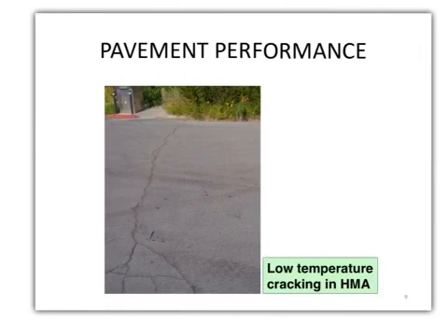If we reach very low temperature, it's going to lead to very high induced tensile strains in the pavement layer, then the thermal cracking will initiate. Or it can happen during a full winter season, when we see a huge difference in temperature between daytime and nighttime, and that will also be the result, as you can see here, a low temperature thermal cracking.